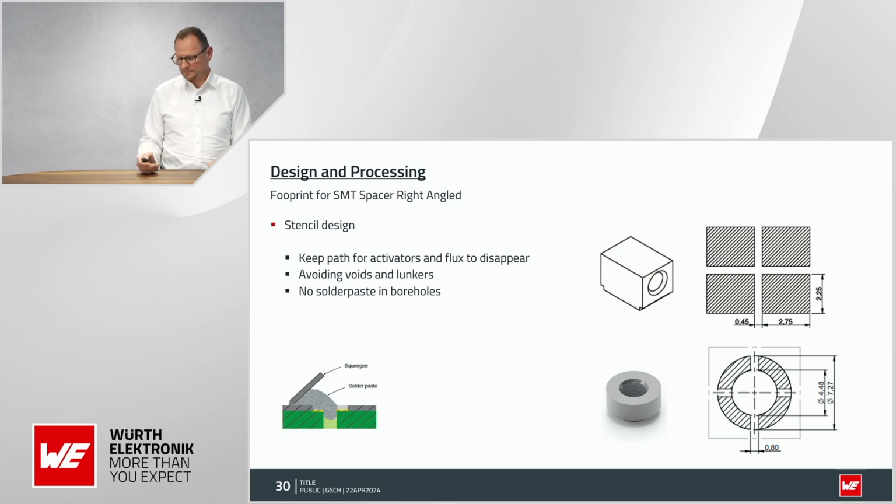also, looking to the round types, you should make clear that no solder paste is going inside of the borehole. Therefore you need to cover it, and only these areas should be plated. You can see how that looks from the side view. This is the PCB, there is a borehole. And this is the stencil in gray, and the solder paste is going to be filled inside these voids. So we need to cover this area so no solder paste can go inside of the borehole.